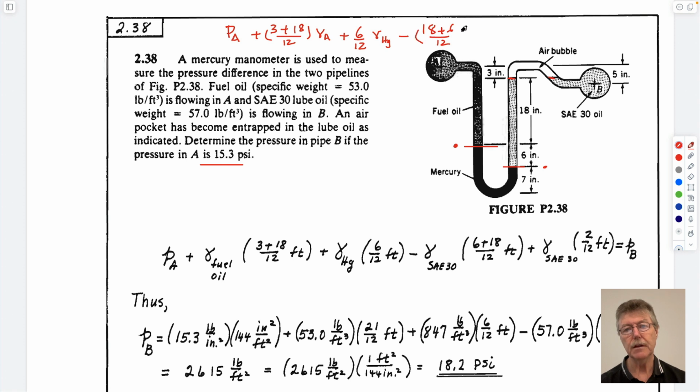Over 12 times the unit weight of fluid B, right? This is a different fluid. So now at this point, that's where we are. We're at the same level here, so we can go across, because dP/dx equals dP/dy equals 0, just for the argument with the bubble in the upturned pipe, and we end up here. And if we want to go down to this point here, it's 3 inches up to here, and it's 5 inches down. So we're going down, so we'll add